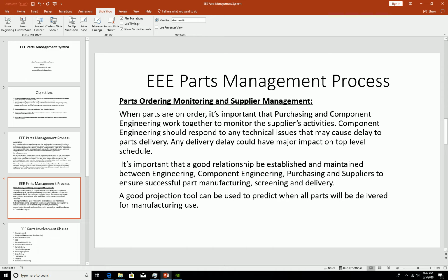And the part is manufactured. Now you have to test to the requirements. Most of the time in space product we purchase to an SCD. If we cannot get a QPL part, you have to create an SCD to purchase this part.